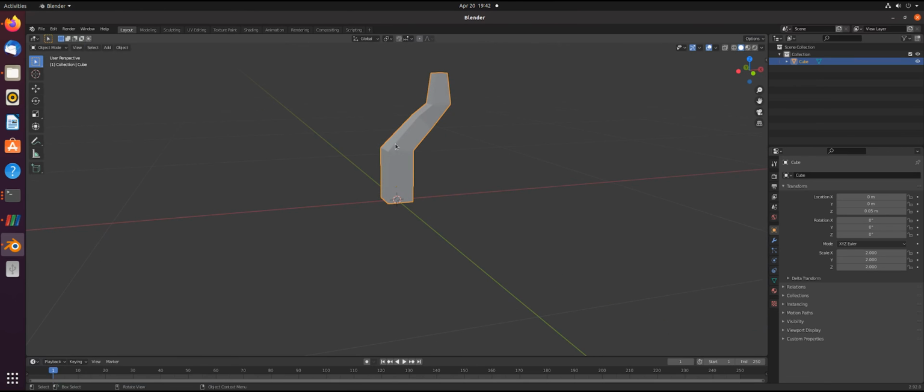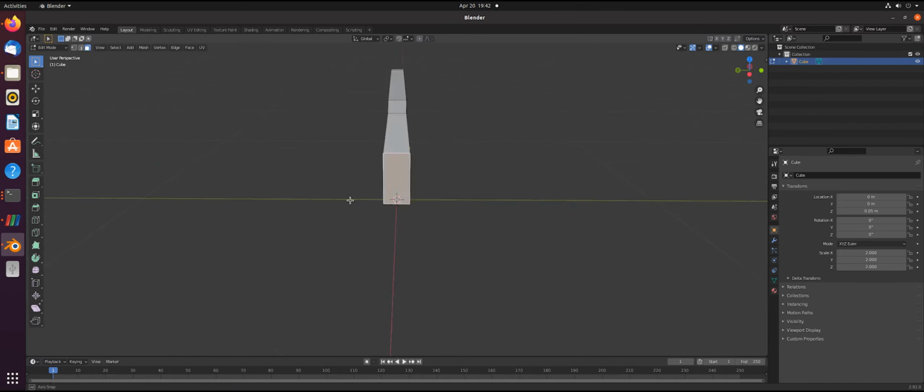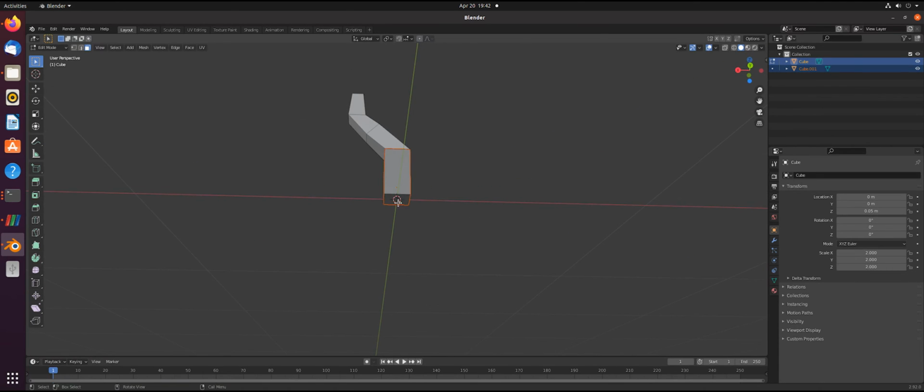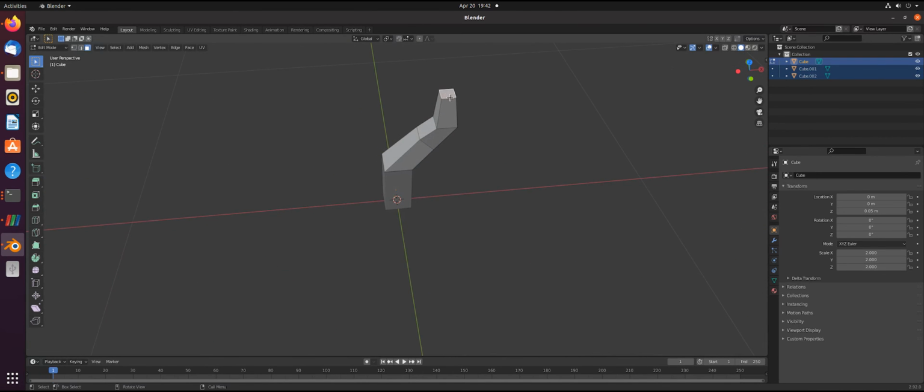After the geometry is modeled, I will select the different faces like the reaction chamber, the chimney, the inlet and outlet of the gas, and divide the structure I created into separate files. Here I'm doing this for the faces of the reaction chamber by selecting all around while holding Shift, and then I separate them by pressing P on the keyboard. You can see it appearing in the top right file browser. Now I repeat the process for the inlet. With the little I button, you can check which part is which.